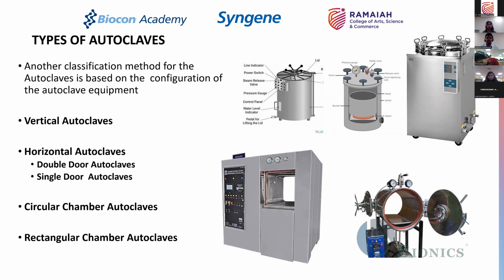So it is very important to choose the right vendor, and to have the right experience of that vendor evaluated before you pick up an autoclave, so that there are no leakages, because leakage is one of the other deterrents to your sterilization process. If you had leakages, your sterilization process will not be efficient. You could have air leaking into the chamber, resulting in wrong pressure and temperature data, which will not give you the stability assurance the way you look at it.